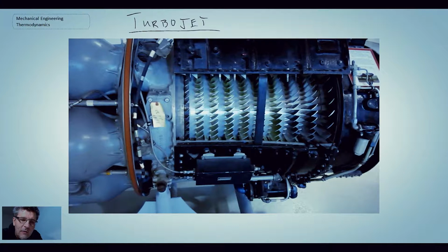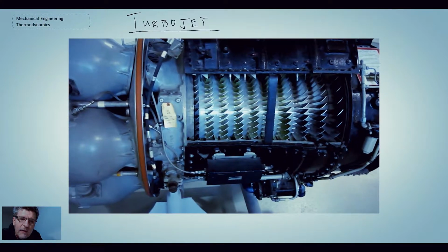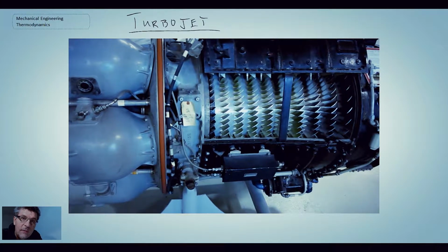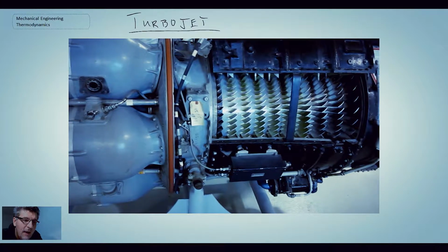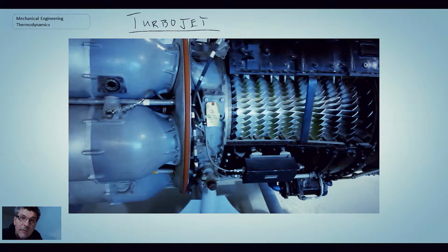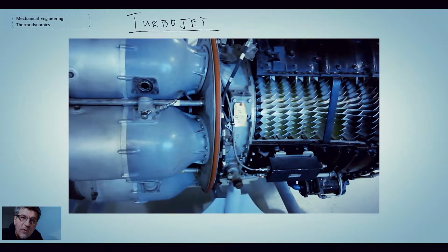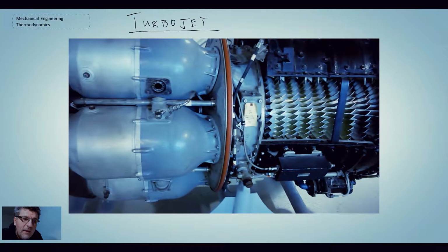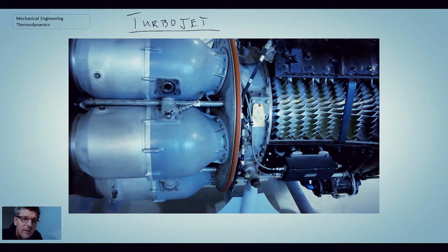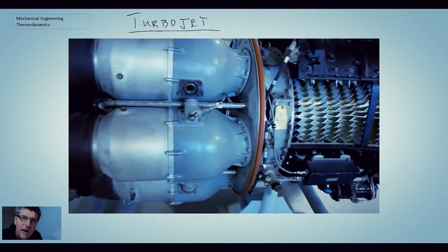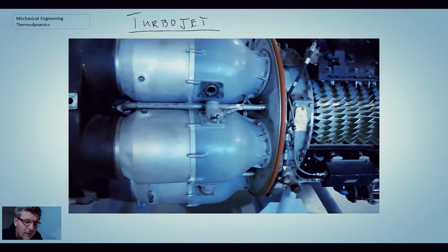And then you leave the compressor stage and move into the combustor. Essentially, they call them tin can combustors that are wrapped around the perimeter of the gas turbine engine. Within these combustion stages, you would have mixing, fuel addition, and combustion inside. You're trying to minimize hot spots.